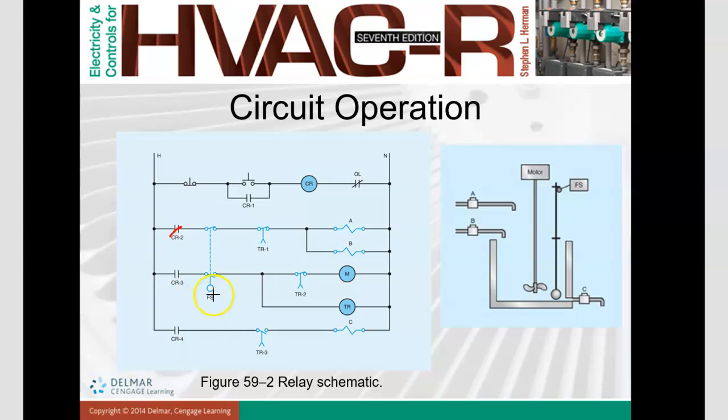The float switch does not reach the level it needs. Okay, so it still has a current. So this one also has a current. So solenoid valve A and B function. So this one will operate. Okay, A and B operate, and then let out the water and also the sugar into the tank.